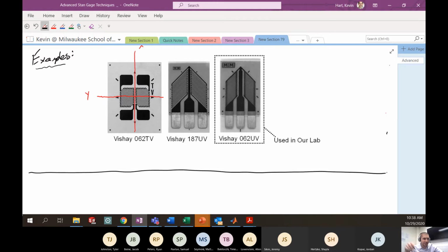So it's nice that we got this gauge on there that can give us the shear strain, but the shear strain at that point that I would measure with that one particular gauge is not limited to just that of torsion or that of transverse shear. I still need to do something else to eliminate the transverse shear effects in my reading of that particular gauge.